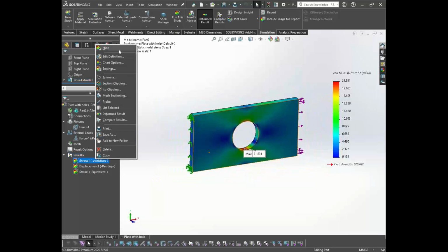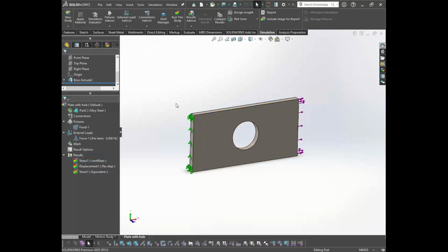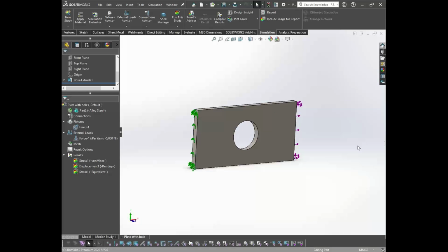So this is how your simulation results are affected depending on the type of mesh, the element size, and the quality you are applying to it. Depending on those factors, your simulation results will vary. Obviously, if you apply smaller elements, that is a finer mesh, to your model, you'll get better results, closer to the actual values. So I hope you understood the basic procedure to follow while performing FEA. Just simply type yes in the chat. If someone has any problem related to this, I'll explain that again.